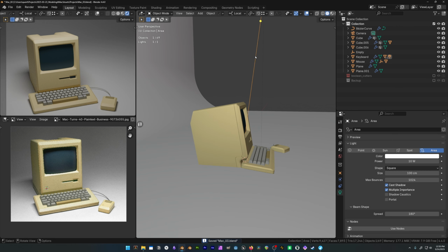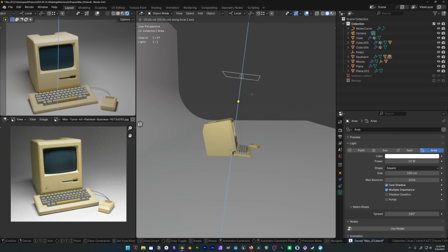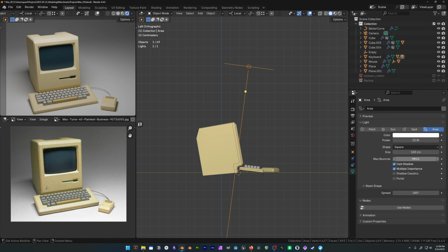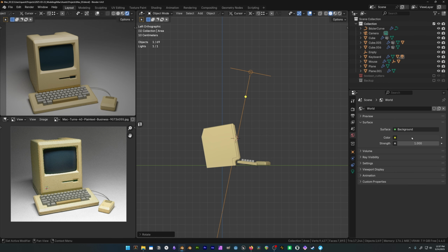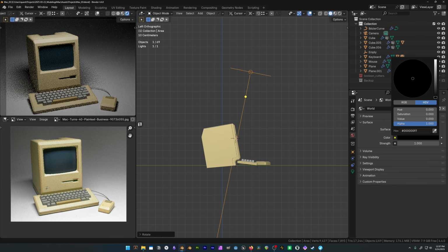And I'm going to brighten this. I'm going to bring this key light in. I also don't want this to spread quite as much, so I'm going to take the spread down. Now that's going to make it maybe like 130 degrees. That's going to make it a lot brighter, more concentrated, so I'm going to bring the power down. I'm going to take the world color down.